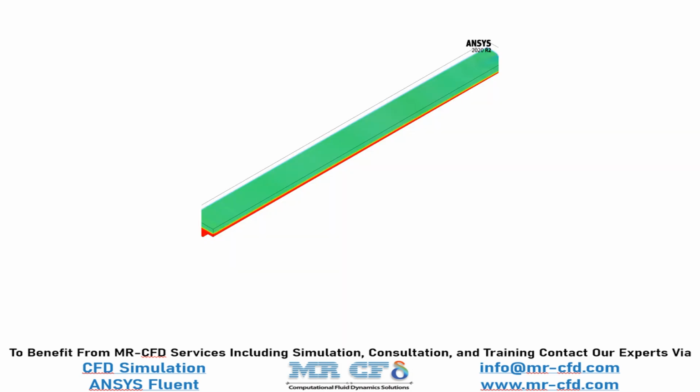In this project, the two-phase flow of water and air inside an open channel is investigated. The standard k-omega model is used for solving the turbulent flow equations. Also, a multiphase VOF model with the open channel setting activated is used to simulate the two-phase flow of water and air inside the channel. The water enters the channel with a mass flow rate of approximately 60 kilograms per second, and its interaction with the air phase inside the channel is simulated.